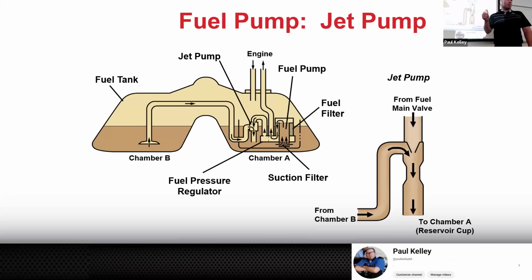It's going to take a while, huh? You're going to be cranking and cranking, and the fuel's like, I'm getting pumped out, but I got to make it all the way up the line, 15 feet to the engine. That's going to take time. So what we do, we put in here a drain back valve, a fuel anti-drain back valve. I know I've got a picture of it, but I just want to point it out while it's very visual. We put a valve in there so that when you shut the car off, that one-way check valve will hold the fuel primed. And if that check valve is bad, what do you think the customer symptoms would be?